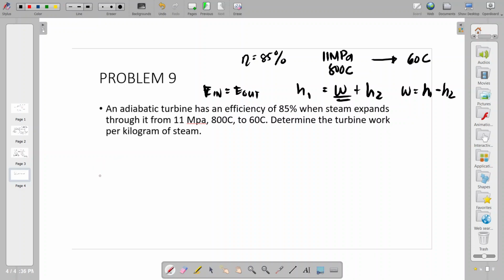So, pag kinumpute na natin siya, hanapin natin si 11 MPa muna sa table 2. Ang TSAT ng 11 MPa ay equivalent sa 318.15 which is lower than 800C. So, ibig sabihin naka-steam ito, yung state 1 natin.